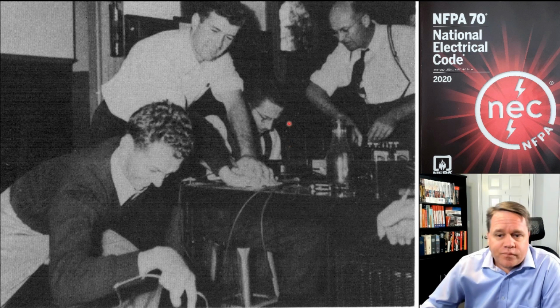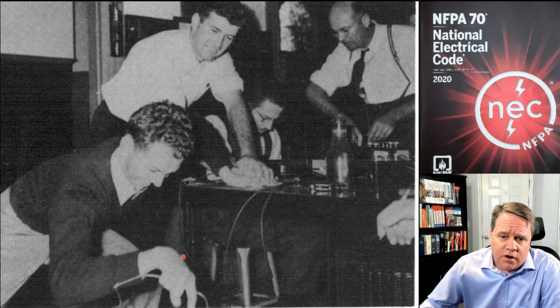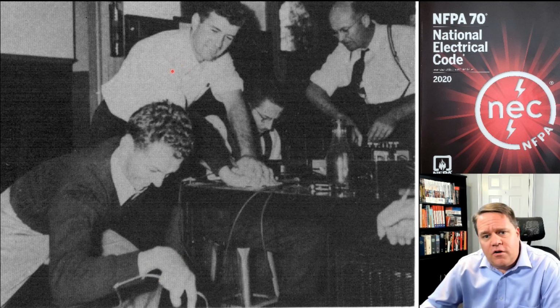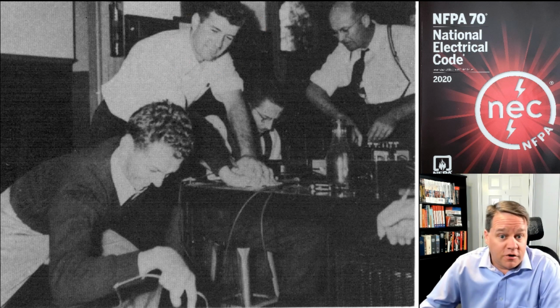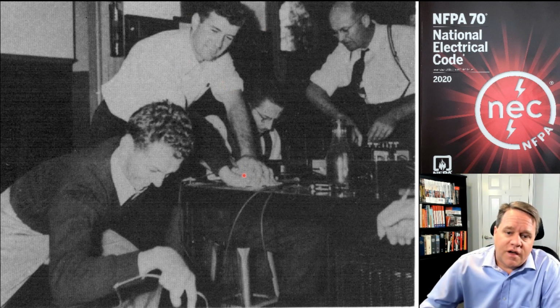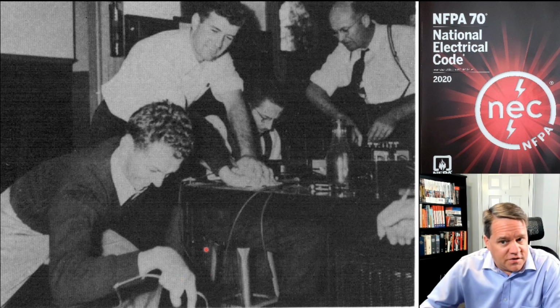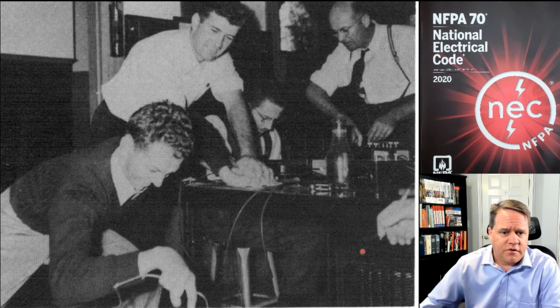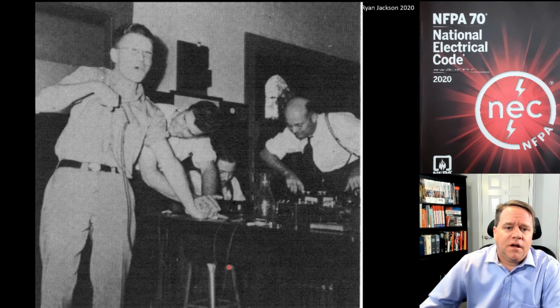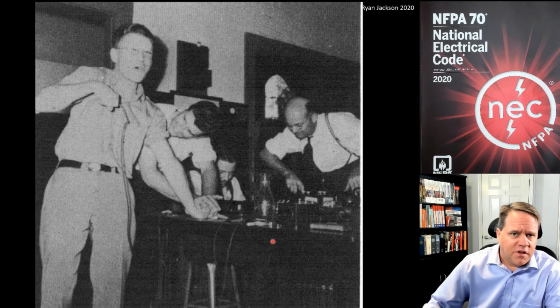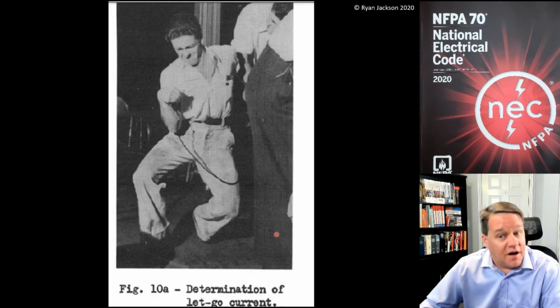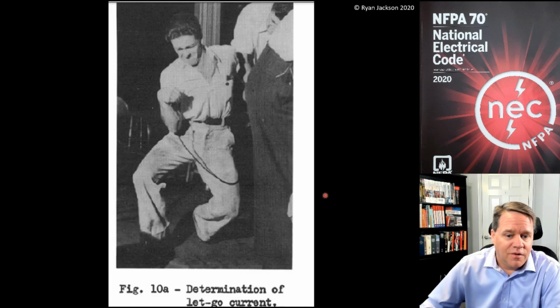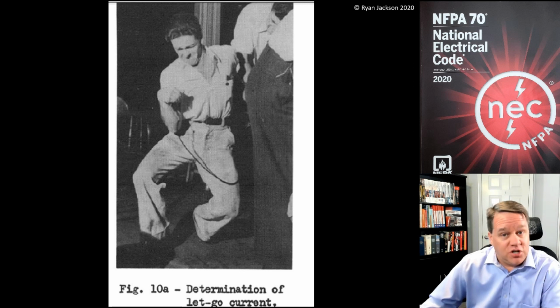Thanks for that. Here's Dr. DeLisle back here administering the test. Here is the volunteer. This guy back here is writing down the test results, and this guy here, who seems to be enjoying this far too much, his job is to hold the guy's hand down and make sure he doesn't let go. So we want the GFCI to trip somewhere between the not painful and painful, this guy experiencing the non-painful and this guy experiencing the painful. So there you go. That is a GFCI.